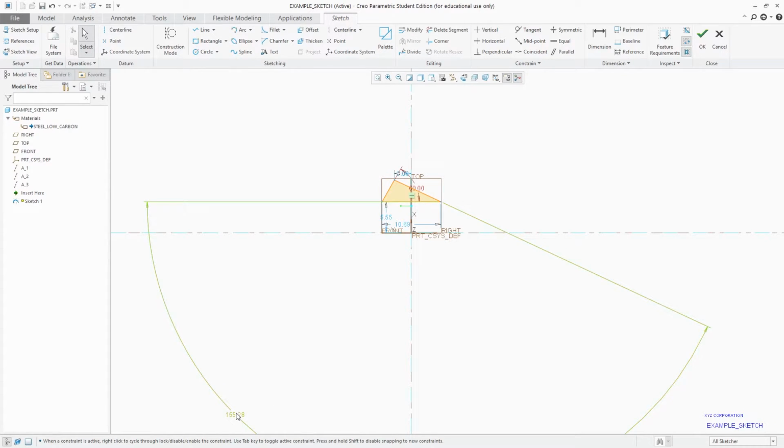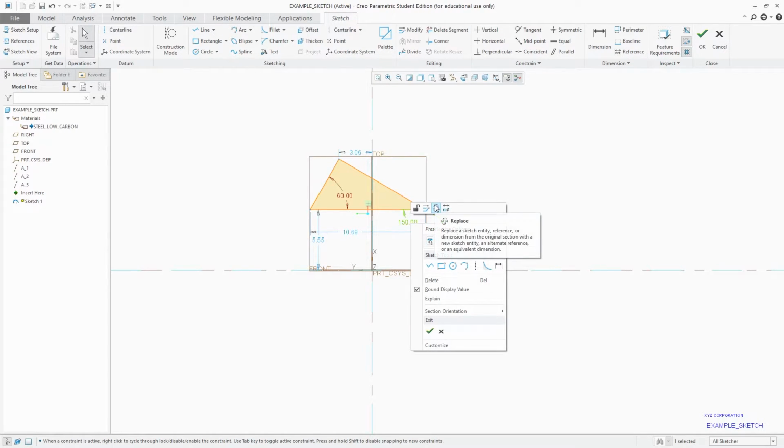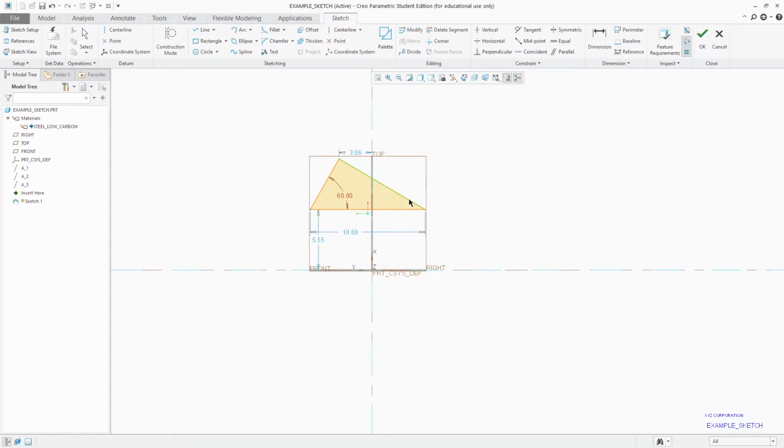and right now it has specified the angular value of exterior angle. It shows me the value of exterior angle, but I need interior, so I can change it. If we want, we can replace it, but it depends on you. Like if you are satisfied, you can simply give this value as 150, and it is again 30. And if you really want to use the interior value, then you can click on replace and again select the same line by pressing Ctrl and just press the scroll wheel, and here we go.